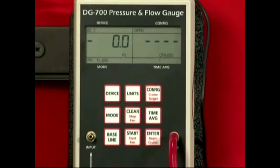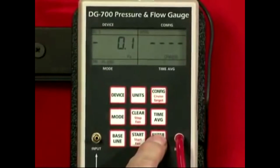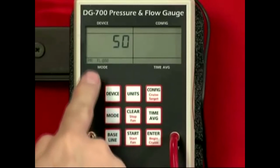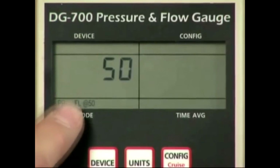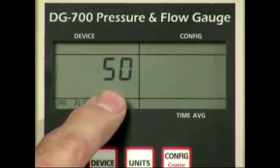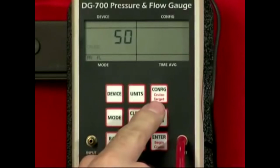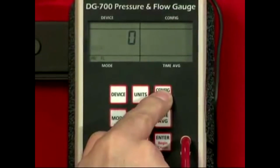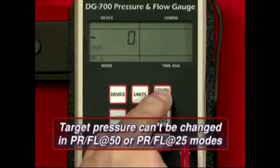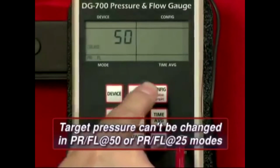When you're ready to begin cruise, press Begin Cruise to enter cruise setup. A cruise target pressure will appear in the Channel A display, and the cruise icon will flash. The flashing cruise icon indicates the gauge is ready to begin cruising, but is not yet controlling the fan. If you are in the PRFL or PRPR modes, you may change the cruise target pressure at this point by pressing the cruise target button. Note, you cannot change the cruise target pressure when in the PRFL at 50 and PRFL at 25 modes.